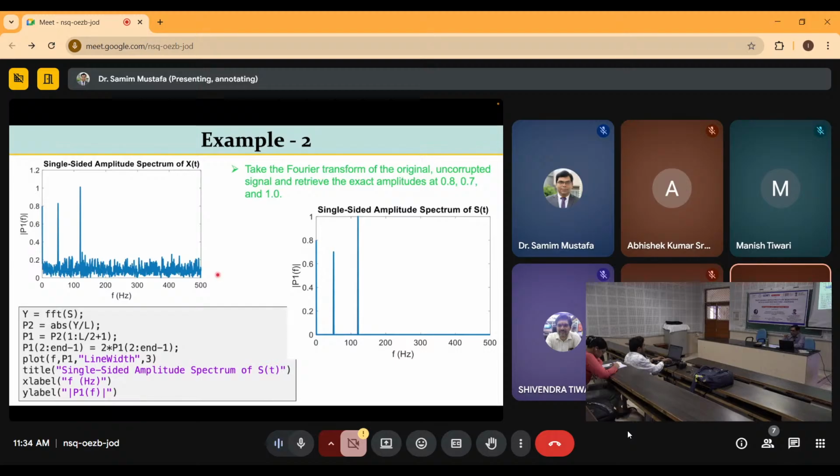The other is ambient vibration happening on the bridge or any civil engineering infrastructure, right? If you assume those are white noise, meaning uncorrelated and independently distributed, they will look like this even if you do the FFT.